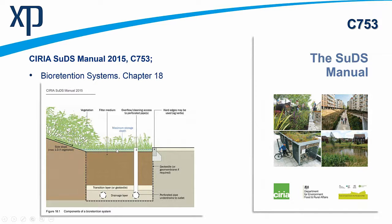Now, where you're in a very tight, high-density situation, maybe a new housing development or a commercial development, we could put in some hard edges that will restrict the actual land take of the bioretention area. So they don't have to be soft edges, they can be hard edges.